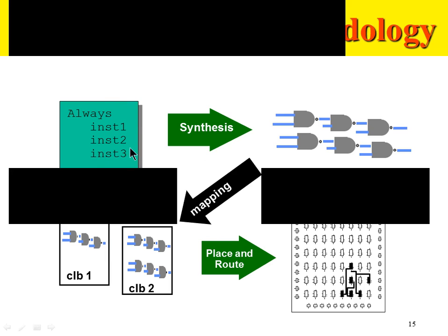You start out with a Verilog or VHDL code, you synthesize it to a generic netlist, then it gets converted to a technology specific netlist. You do the backend process of placement and routing. Any timing analysis, static timing analysis, is done after placement and routing. Finally, the chip is programmed for the functionality which was described in Verilog format.